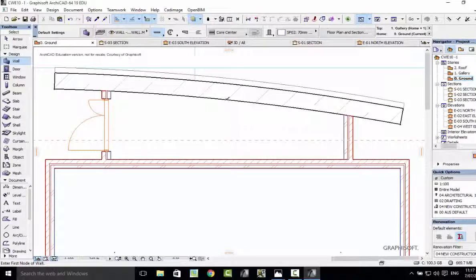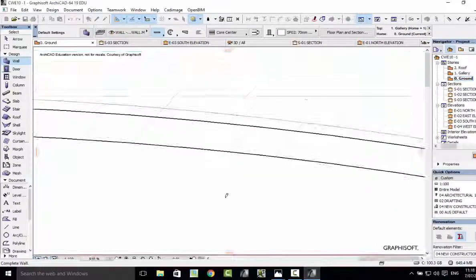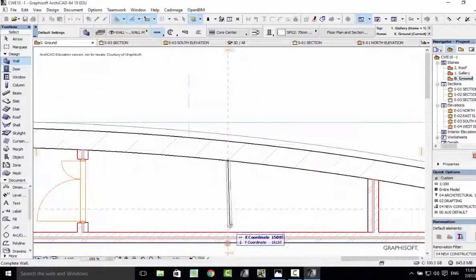Now the first wall needs to go in the center of the wall here, the center of the building. Now there is a center mark here, but we're going to use a guideline, and we know that the overall dimension of this building is 10 meters. So let's grab a guideline onto the edge, and we'll move that 5,000, just 5 meters, and that will give us our center point. Now to insert the wall, we'll come through to the other wall.